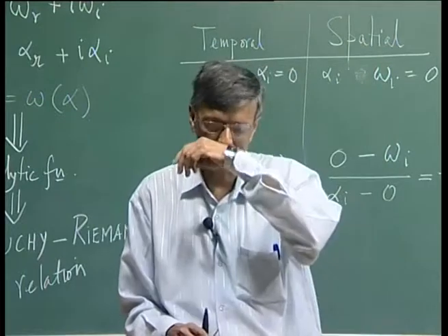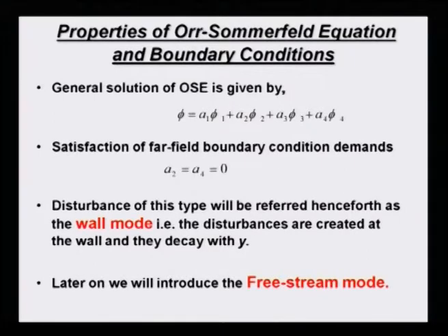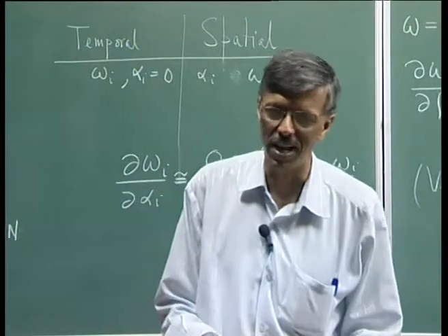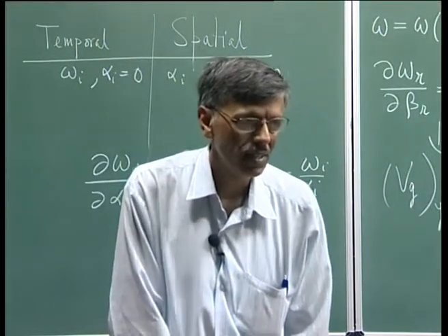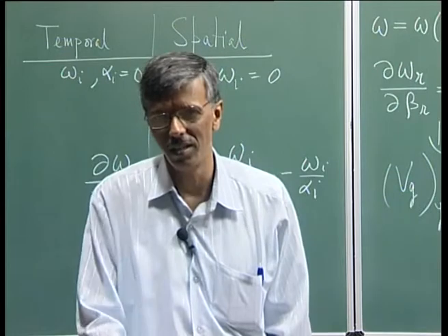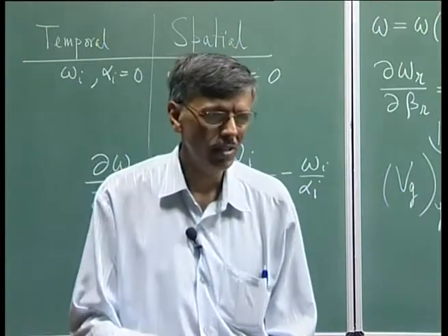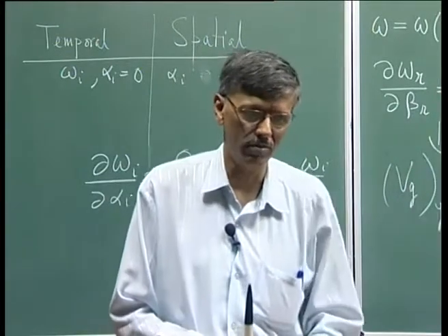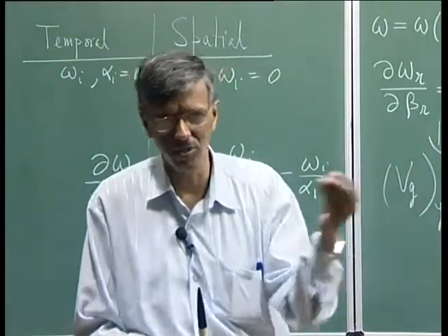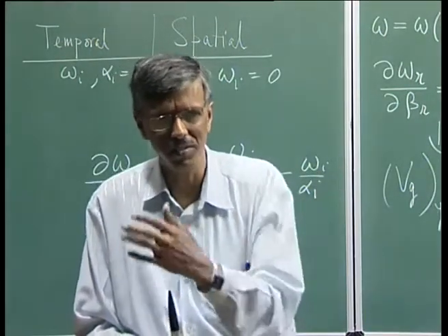In fact, I will show you some of the lab experiments we did about 10 years ago, where we set up this so-called free stream mode. A good example also comes from the engineering side, when you look at what happens inside a gas turbine. There you would see, be it in the turbine or in the compressor. Take the compressor, it is a cleaner flow, but you have the stacks of rotor and stator. So, from the stator what do you get? You get vortices, right.